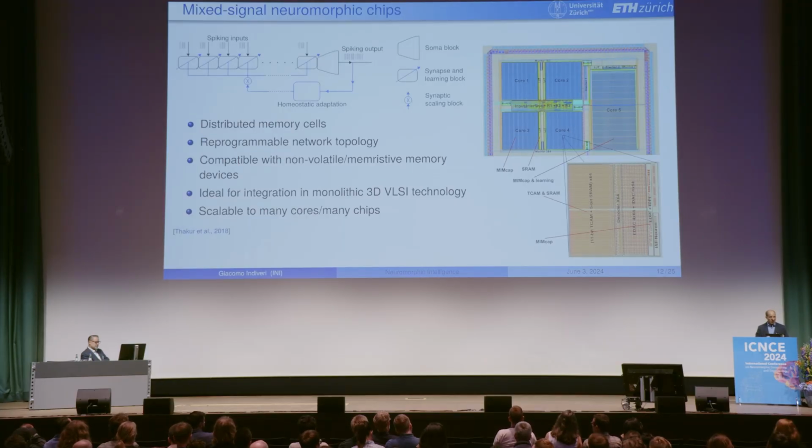The problem with analog is that capacitors don't scale as well as transistors, so we still have to pay the price of area. If we want to have 256 copies of the neurons, they do take up area, so that's the price. There is no free lunch. We do have low power, but we do pay with using a large area for a neuron and an array of neurons. The other big area-consuming part of this chip is actually the digital circuits that are routing the spikes across neurons.